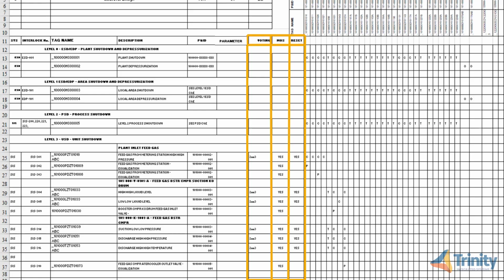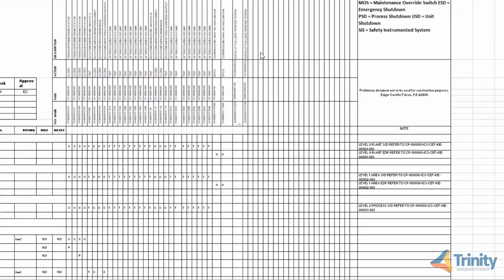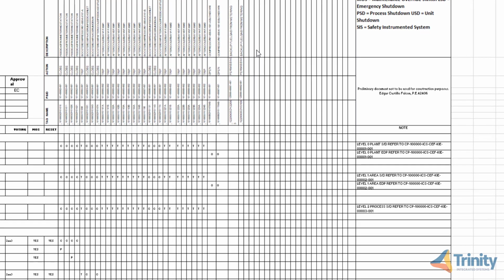Similarly, on the output side, we look at outputs which have latch, outputs which have reset, outputs which have feedbacks, and other outputs that don't have feedbacks. Some have valve position fail monitoring. You will also have to look at the outputs and assign typicals that are available in your project.